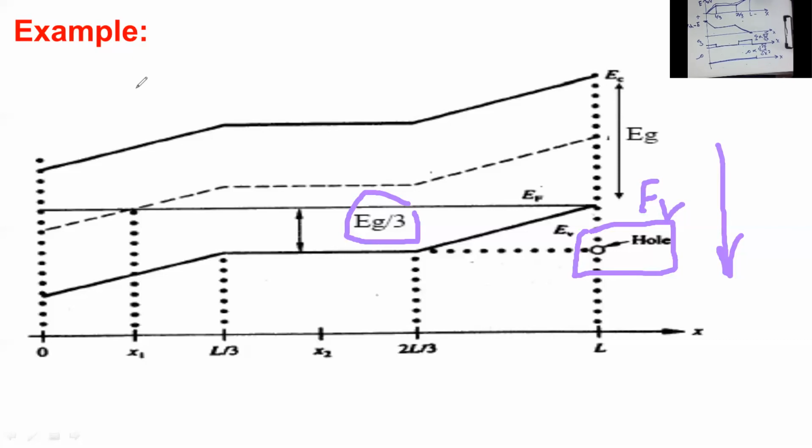The sign is that you have a flat Fermi level. Whenever you have a flat Fermi level, your device is under thermodynamic equilibrium. Whenever the Fermi level starts to split, it's not a thermodynamic equilibrium. So if I ask you whether your structure is under thermodynamic equilibrium, you will tell me yes, this device is under thermodynamic equilibrium.